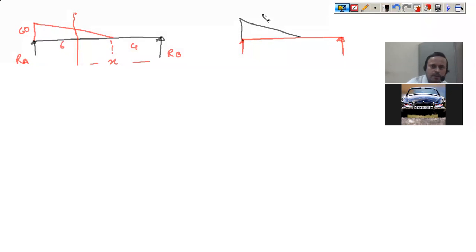so if you try to solve it from this side, what happens is, if this is x, now this is a trapezium. So it is not that the area of a trapezium cannot be found out, but the system will be getting difficult. So it is advisable that whenever you have a loading condition like this, then start from the side where you end up at a triangle. You should not end up at a trapezium, because if you end up at a trapezium, the problem will be getting very difficult.